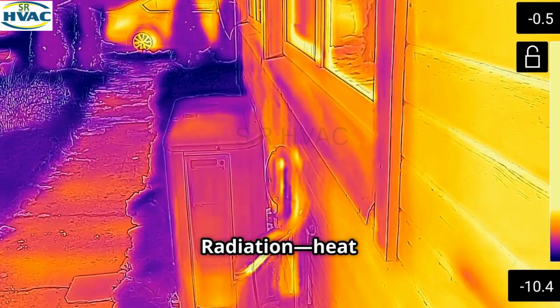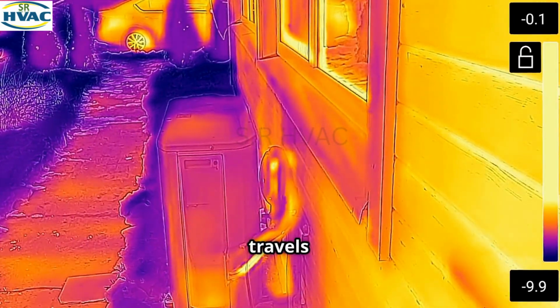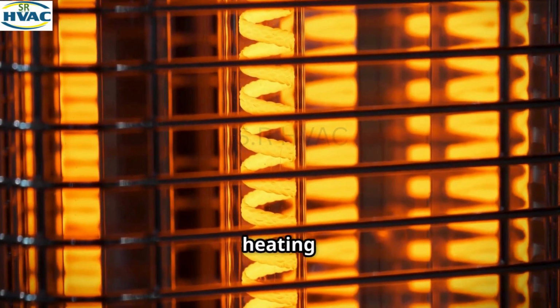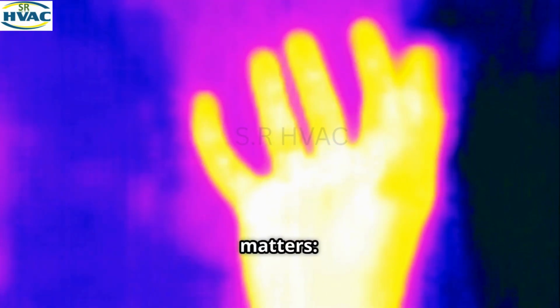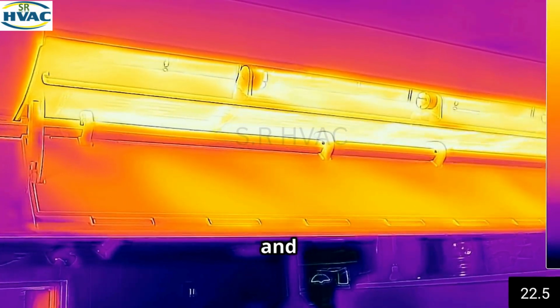Radiation. Finally, we have radiation, heat transfer through electromagnetic waves. It doesn't need a medium. Heat travels even through a vacuum. Real world HVAC example. Ever stood near a radiant floor heating system or an infrared heater? You feel the warmth even without air movement. That's radiation. Why it matters? In buildings with large glass windows or uninsulated roofs, radiant heat gain can drastically affect indoor temperatures and HVAC loads.